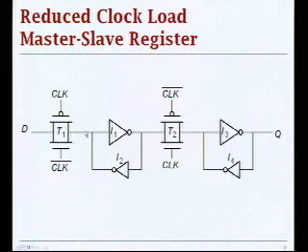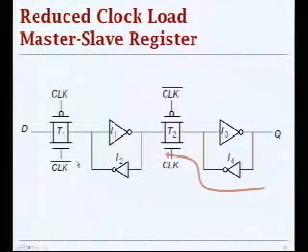You will burn some extra power to do this overpowering approach, but that amount of power is going to be less than the clocking power that you would have otherwise if you had to break the loop. So that's basically the trade-off over here. And there is a problem with this scheme in this back path, that any disturbance at the output may actually be reflected back all the way through.